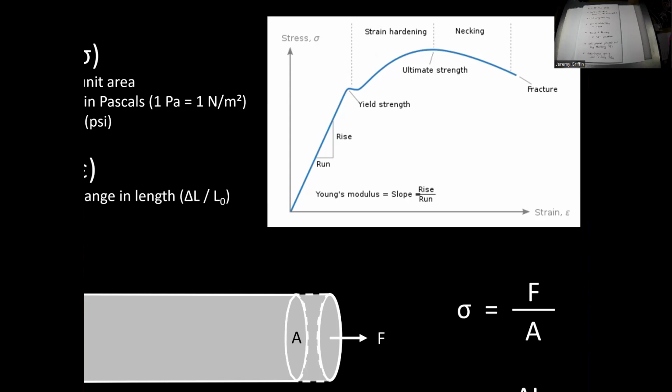So the rest of this curve could apply to metals like steel. Steel might have this whole top section where there's some ultimate strength that's even greater than the yield strength, possibly. But then you keep stretching it. You can stretch, stretch, stretch. It actually gets weaker. That's why this tapers down until bam, it ruptures right there.